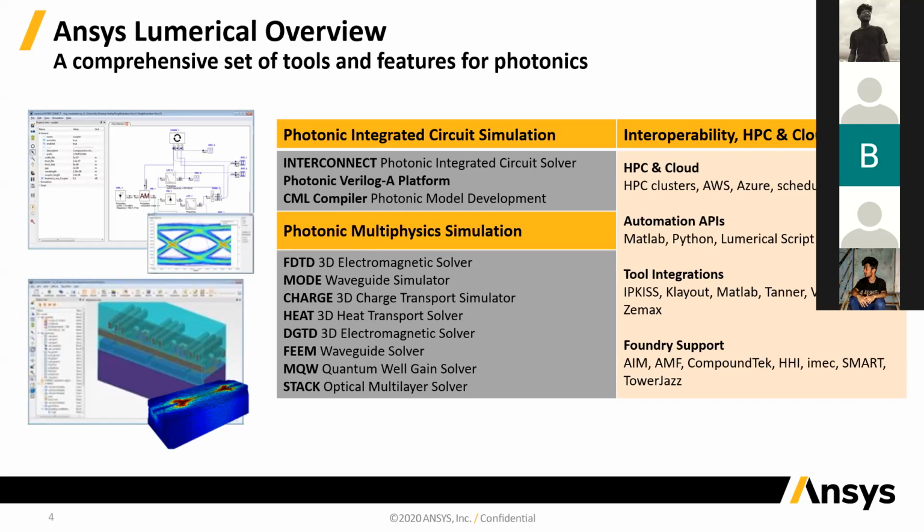But then also you have to consider the electrical side of things. You have to figure out how electron hole pairs are getting generated, how they're getting collected at the contacts, and if there are losses happening during that transport. So it's a multiphysics simulation requirement. You need to simulate optics, you need to simulate electronics. And that's why the multiphysics simulation suite offers you different types of solvers for different simulations.